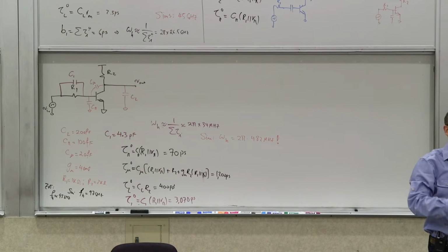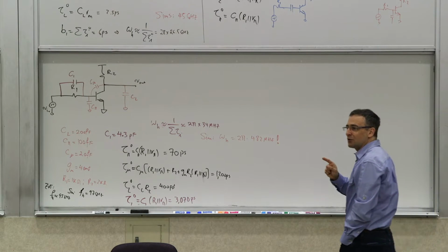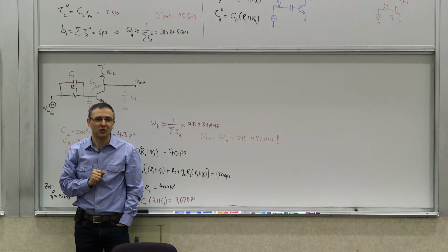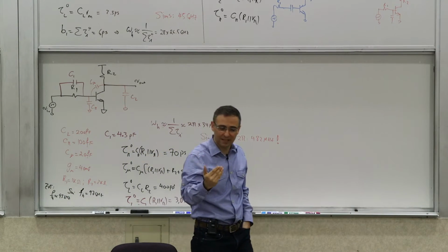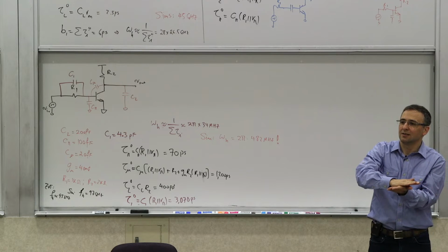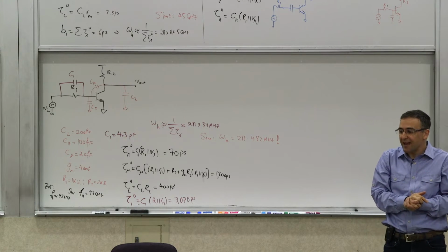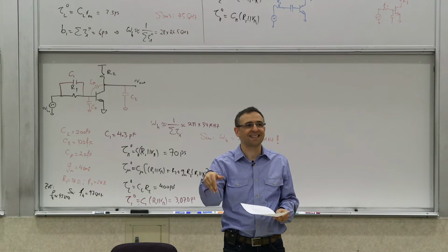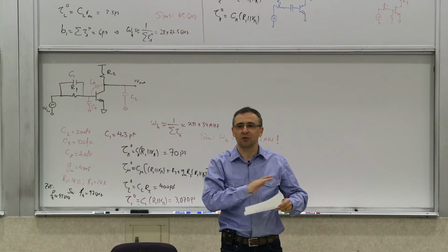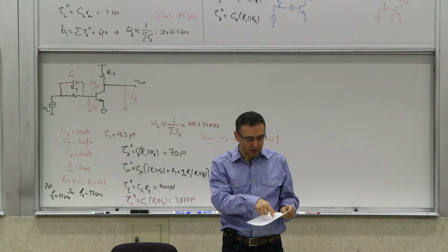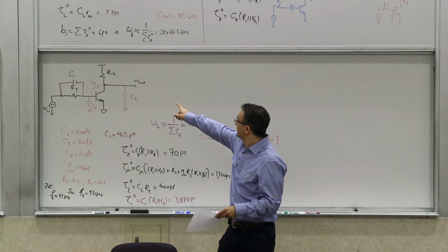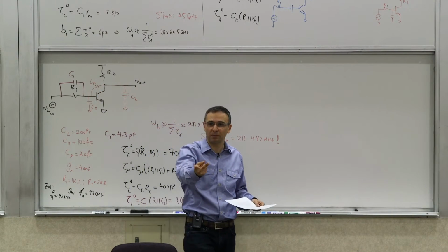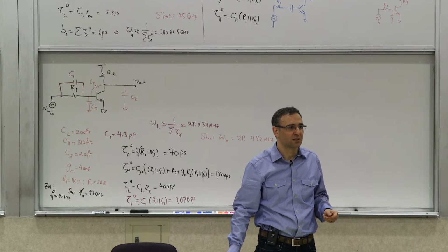Cancel out that dominant pole. Yes. So we picked that value of C1 to be sitting dead on top of that first pole, to the extent that you can. So that capacitor came in, that zero came and sat right on top of that first dominant pole. So now what you're hit with is your second pole. What you see in that Bode plot, that first drop, is that second pole, because your first pole you've already killed. And then what you see when it flattens out is that right half plane, very high frequency zero, due to this guy, which was flipping the polarity. Does it make sense?